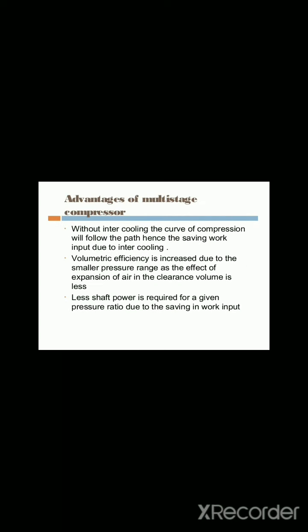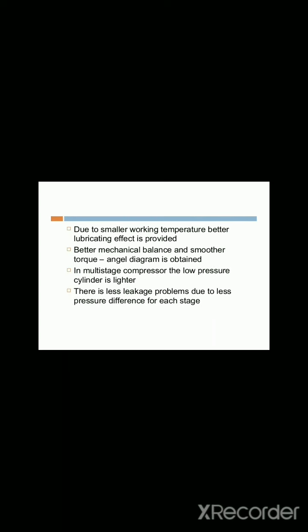Advantages of a multi-stage compressor: without intercooling the curve of compression will follow a different path, hence there is a saving of work input due to the intercooling. Volumetric efficiency is increased due to the smaller pressure range, as the effect of expansion of air in the clearance volume is less. Less shaft power is required for a given pressure ratio due to the saving in work input.